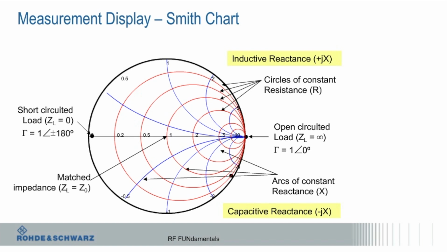So what you can do is add these arcs of constant reactance. So this is adding something that's a complex impedance, right? I can move along this curve here by adding or subtracting some amount of capacitance or inductance. If I want to move down, I'm going to add capacitive reactance. If I want to move up, I'm going to add inductive. And the goal is basically to get you onto this circle, and then you're probably going to have to add some real impedance to it, simply said.